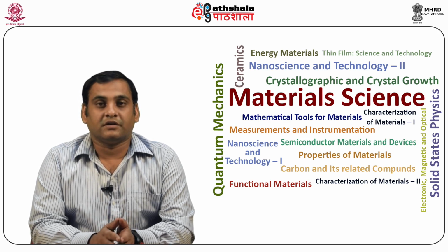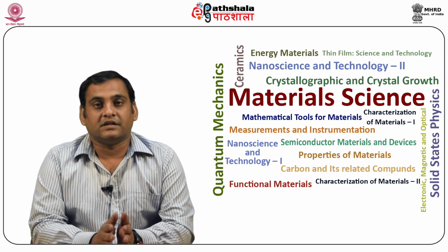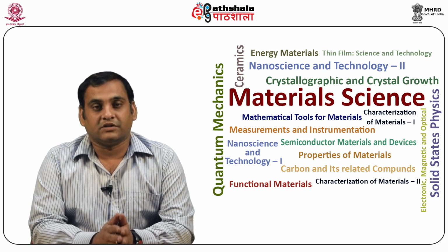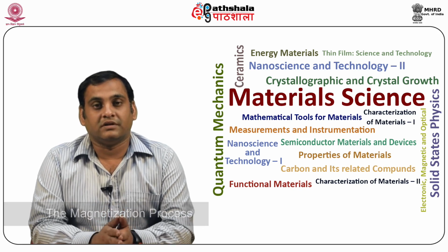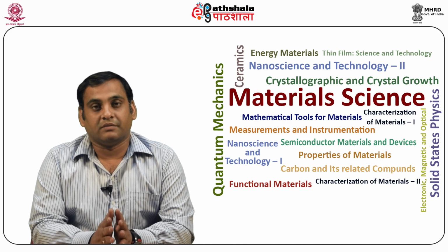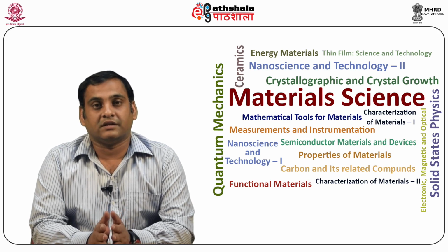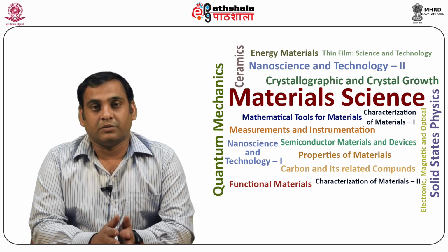If we consider a magnetic material with B and M curves as shown in figure 4, the integrals are as indicated in the figure caption. The energy, the integration from 0 to M of mu 0 H prime dot dM, expended to magnetize a sample is related to its anisotropy energy, including shape anisotropy, since the magnetization process in the external field depends on the orientation of the sample. If the M-H prime relation shows hysteresis, energy is expended on cycling the field H prime. For example, figure 4b shows the energy expended to magnetize the sample to remanence.